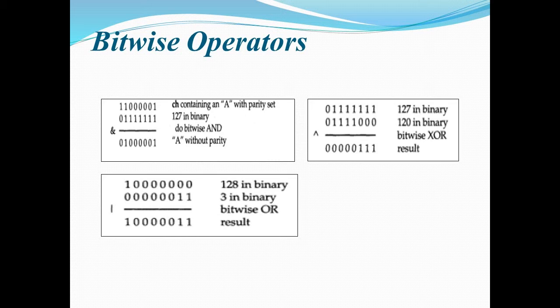So in this slide we are going to see how these bitwise operators work. Here I have taken some hypothetical data. The first example is a bitwise AND operation. Here you can see the bit pattern 1 0 0 0 0 0 1, and after that the pattern 0 1 1 1 1 1. Now what if I perform an AND operation? It will go bitwise. So 1 and 1, the result will be 1. Now the next combination is 0 and 1, so according to the AND truth table, it will be a 0. After that it will be a 0, and you can look at the D6 bit. It is 1 and 1, so the result is 1, and at the D7 bit it is 1 and 0, so the result will be a 0. So this is called a bitwise operation. We have studied this bitwise operation in the 8085 and in the 8051. They are the very same, performing just a bit by bit operation.